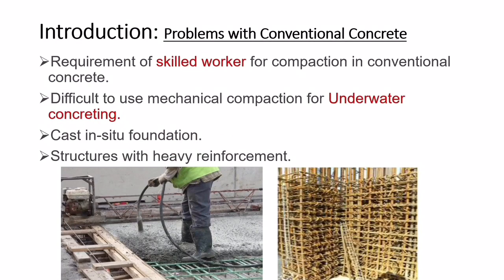Problems with conventional concrete: requirement of skilled workers for compaction in conventional concrete, difficulty using mechanical compaction for underwater concreting, cast in situ foundations, and structures with heavy reinforcement. As you see in the right figure, in a heavy reinforcement structure, if we cast in conventional concrete, that cannot fully fill the formwork.